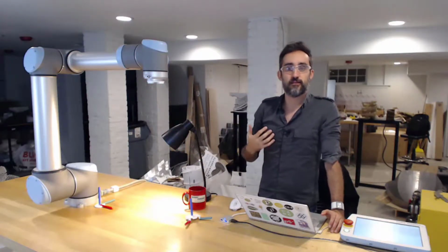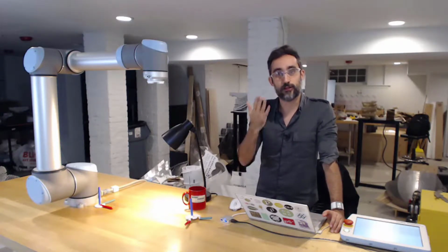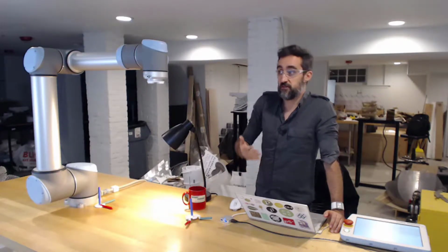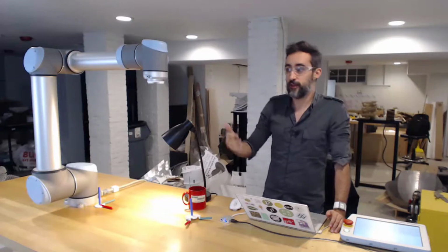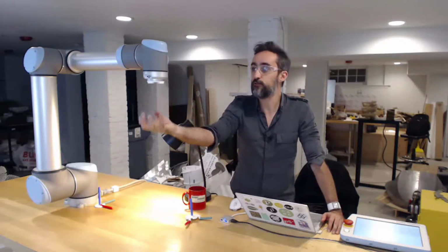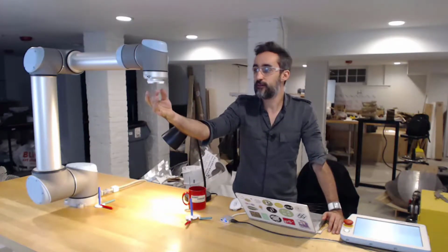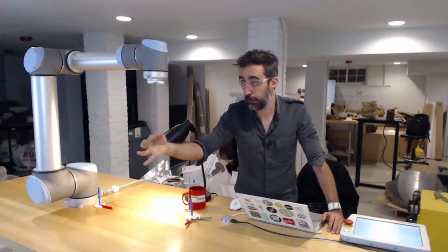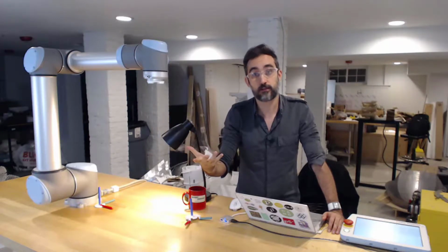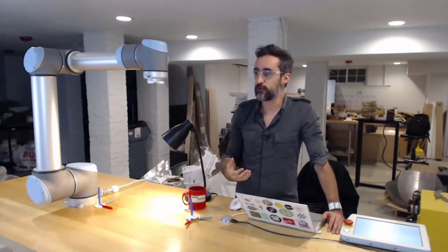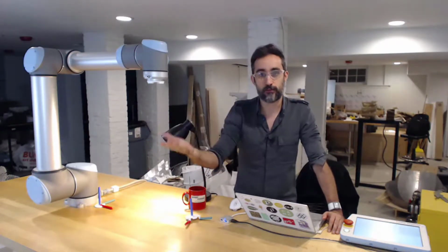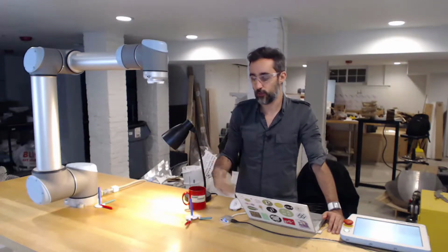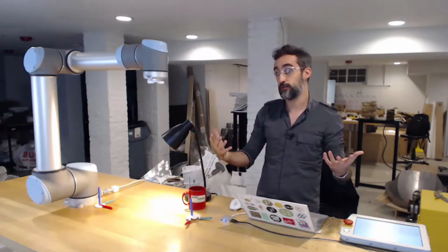But that's very unlikely the point that you will be interested in using, because if you're using an industrial robot arm, then you probably have some kind of tool attached here, and then the point that is important for you is not the center of this, but it's somewhere here or here or here, depending on the characteristics of your tool, right? So it will be that point that is important for you and that you want to use for motions, for rotations, etc.